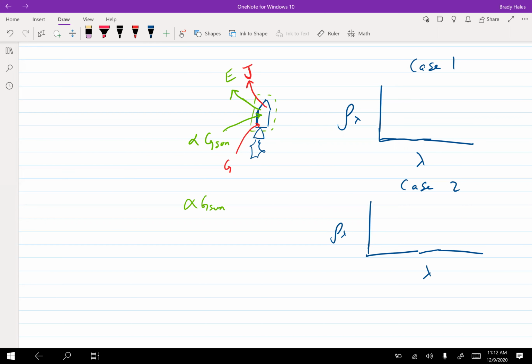So let's say that the reflectivity here is going to be 0.5. But then let's say we use a special case of paint, where it's 3 micrometers, okay? So the reflectivity is going to be 0.9 until 3 micrometers. And then let's have it drop to 0.2 at 3 micrometers. So then the question becomes, should we paint the rocket?